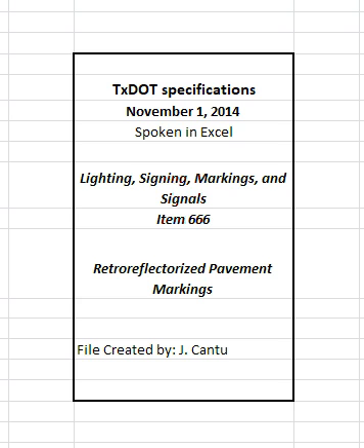That are retroreflectorized with drop-on glass beads, and using personnel skilled and experienced with installation of pavement markings. Remove all applied markings that are not in alignment or sequence as stated on the plans, or in the specifications, at the contractor's expense in accordance with Item 677, Eliminating Existing Pavement Markings and Markers, except for measurement and payment.